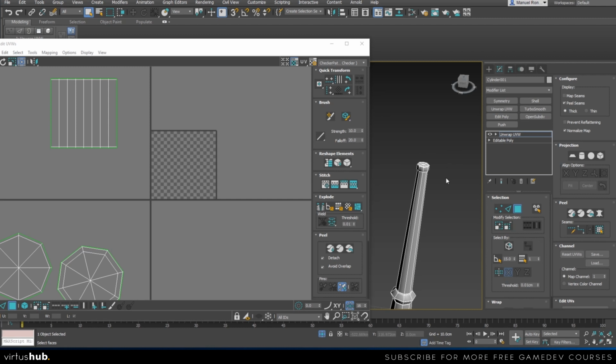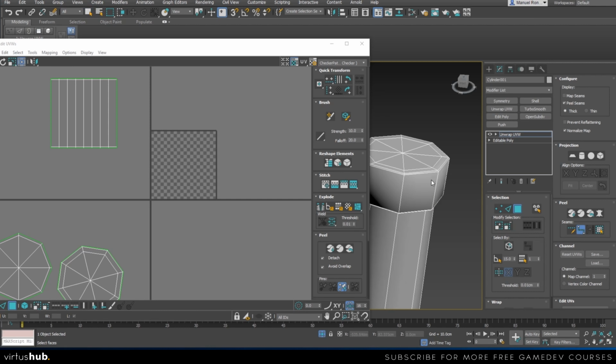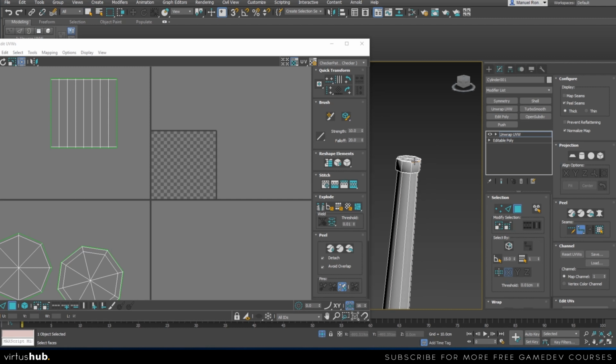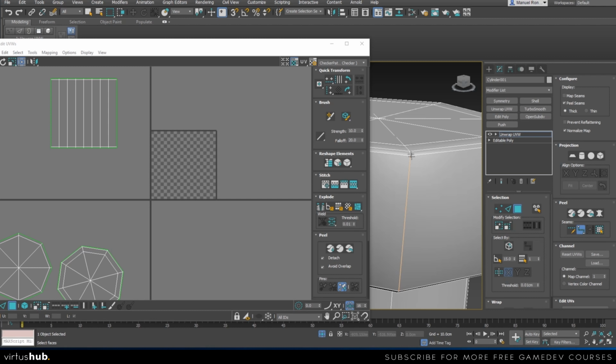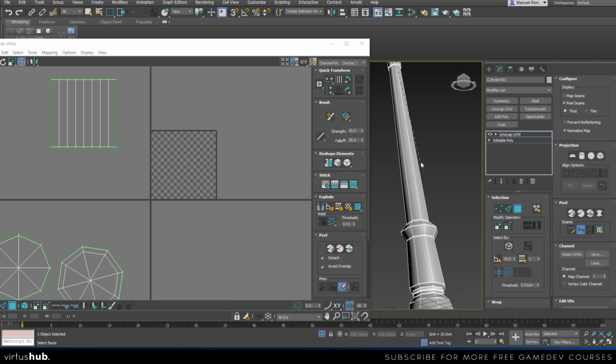We're going to do just that, only we're not going to use any sharp objects. We are going to use the point-to-point seam tool. It's right here. So let's say we want the seam to be over here. So I'm going to click this, and the good thing about this tool is that it follows exactly the same loop. So this is another reason why I like to have quads whenever possible.